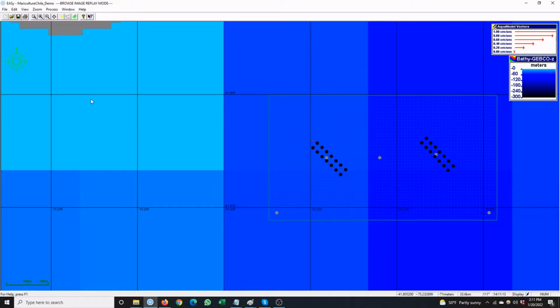Fecal and feed wastes leave the pens and sink to the bottom based on bathymetry and current flows, and are deposited and resuspended based on specified benthic parameters. Current flows can either be based on 2D single-point datasets such as output from an ADCP current meter, or can use 3D circulation models including FVCOM, ROMS, and various forms of Delft, providing a basis for analyzing the effects of convergent and divergent current flows as well as eddy circulation. In this example, the simulation uses a 2D single-point time series of current velocity and heading at various depths.